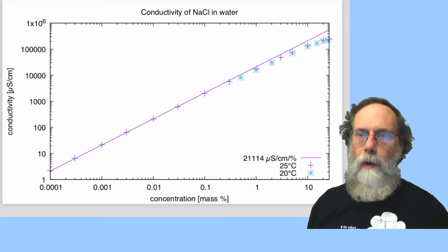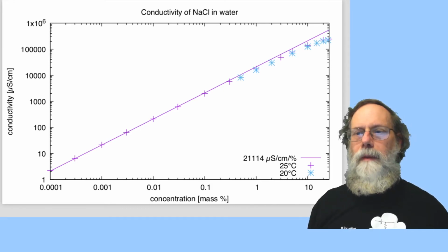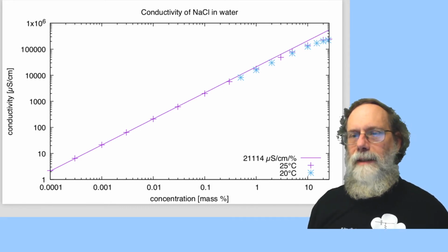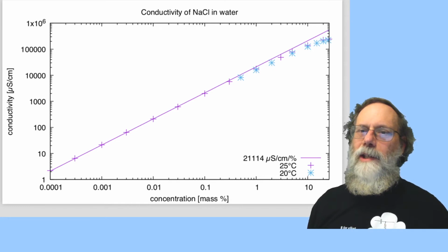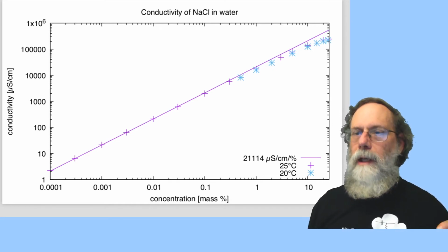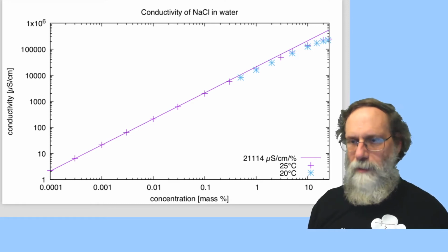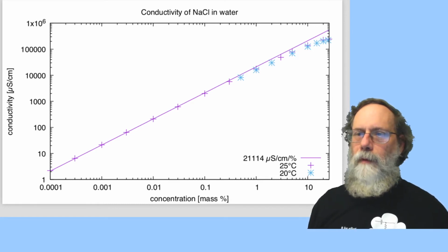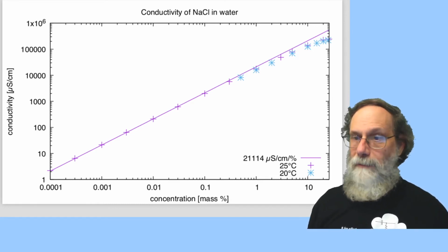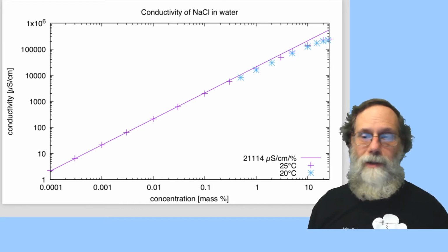And so when one's measuring the salinity of something, generally you measure not just the conductivity but also the temperature, so that you can correct with some standard formulas for the effective temperature as well as in order to compute the concentration.